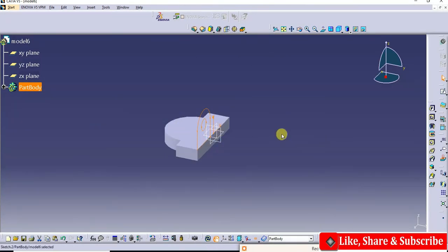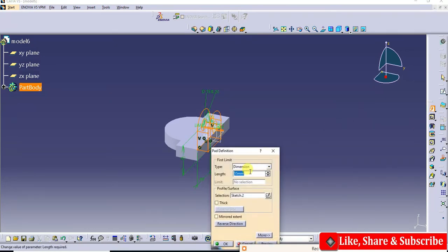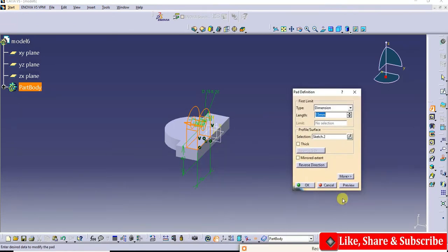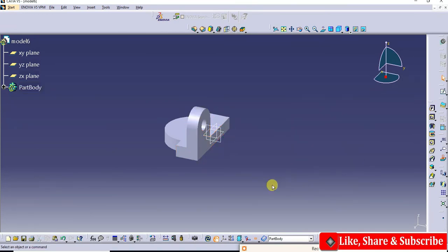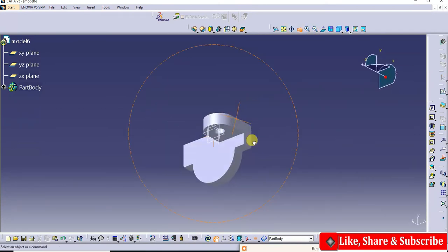I'll use the pad command. The thickness of this pad should be 15, you change the direction here, and you can preview this. This is a 15 mm pad. Now I'll rotate this. So this part has been created.